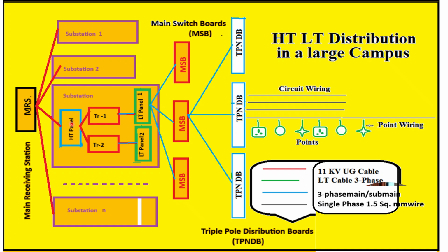The ST panel is connected to transformers, a number of transformers, in this case only two, and this transformer converts 11 kV here to 433 V directly, and this is feeding the LT panel, so-called medium voltage panel.